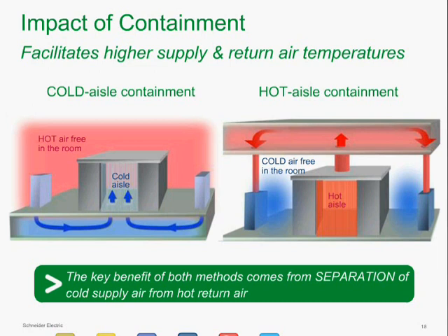But what we're trying to do here, in addition to making the cooling units more efficient, is to, again, drive up the delta T to the indoor cooling unit and also the return water temperature to the chiller plant, for instance, so that we can get more efficiency both inside and also outside.